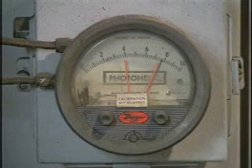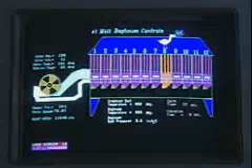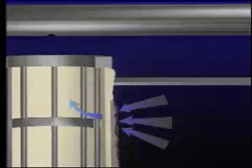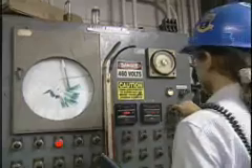Shaker compartment pressure drops that are not zero during cleaning and reverse air compartment pressure drops that do not change sign during cleaning indicate a failure of the dampers to isolate the compartment. Changes in the cleaning system parameters can affect performance, and these should be checked. Increases in the frequency or duration of cleaning can result in overcleaning and in excessive bag wear, while decreases in frequency or duration can result in undercleaning and increased pressure drop. These parameters can be evaluated from timers in the control panel.